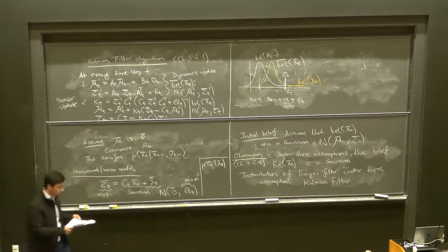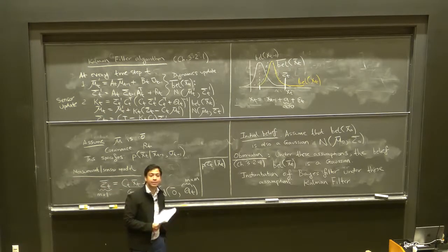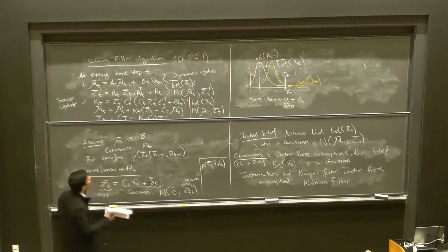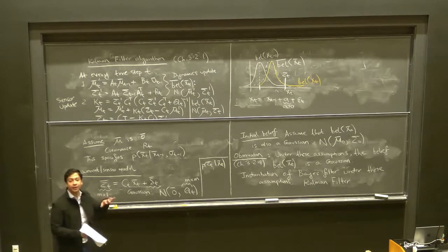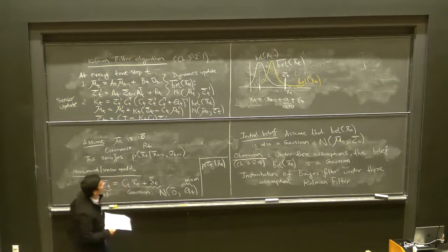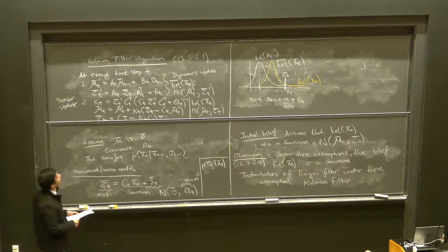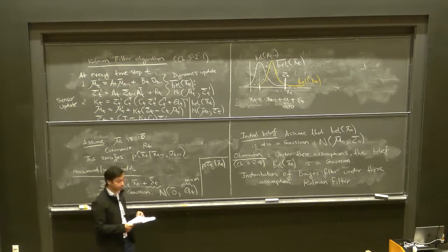All right. Okay, so when do you think the Kalman filter is not useful? It is useful when the dynamics are approximately linear. If you're hovering, we implemented the LQR controller by linearization. So if you can approximate your dynamics with a good linear approximation, then the Kalman filter is good.